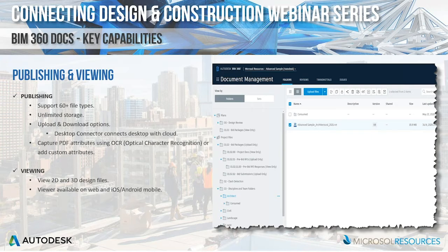It essentially acts as a drive on your computer that can be accessed through Windows. We can even capture information or attributes, as Autodesk refers to them, from your PDFs using quote-unquote OCR, which stands for optical character recognition. What that breaks down to is, for example, when you upload your PDFs to BIM 360, you can create a template that will read the sheet number, the drawing title, etc. Whatever you tell it to, it will automatically read that information and name it correctly within Docs as you upload more and more PDFs with that same layout.